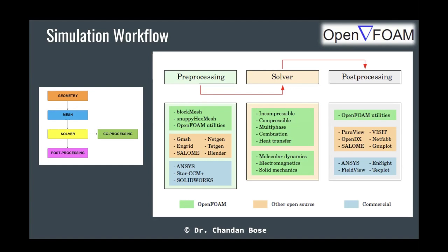So you give the geometry and then it cuts the boundaries of the body to give you a mesh. Rest, GMSH and Salome are two very powerful open source geometry and mesh processing softwares, which I often use. And of course, for very sophisticated, complex 3D geometries, you can also use the commercial versions of ANSYS meshing or StarCCM, SolidWorks for geometry, etc.